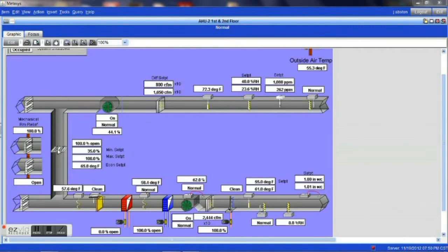This section here, this set of dampers, as well as these two sets here, are representative of dampers that are used in the economizer mode, as well as our mixed air, as well as exhaust. When we are economizing, when we are using outside air basically to cool the building instead of using our chiller system, you're bringing in a large volume of air into that building. One of the things this will do is actually pressurize the building.